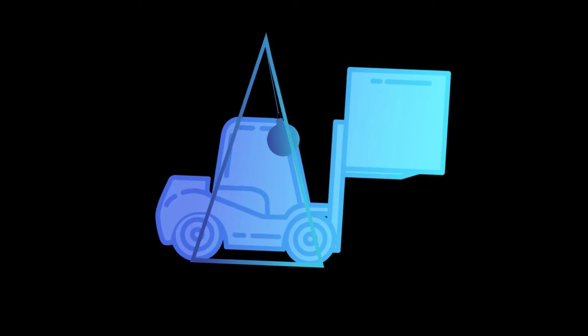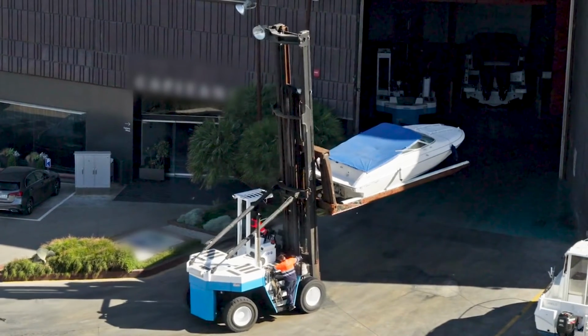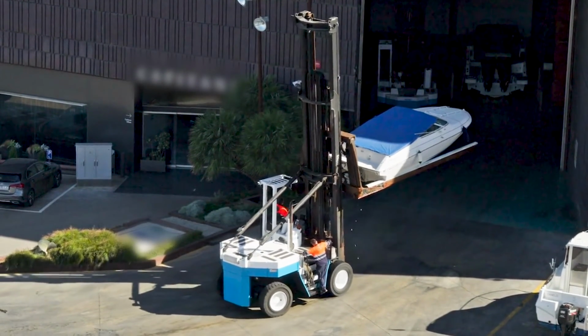When the load is kept low, the stability pyramid is short and sturdy, with the center of gravity securely positioned within the structure. As the height of the load increases, the stability pyramid becomes tall and narrow, making it easier for the center of gravity to exit the narrowing limits and lead to a tip over. Essentially, the higher the load is lifted, the more precarious the system becomes. To prevent the risk of a tip over, be sure to keep the load as low to the ground as possible, especially when traveling.